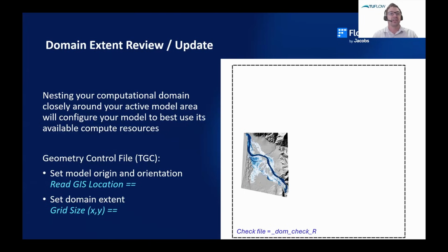Let's start with the domain extent review. When you first build your model, you should be trying to nest your computational domain as nicely around your project area or your total model area as possible. If you don't, then you're really just allocating compute resources unnecessarily to other parts of your model where nothing's happening.